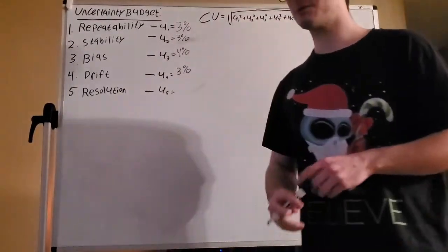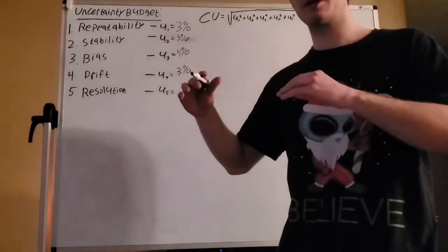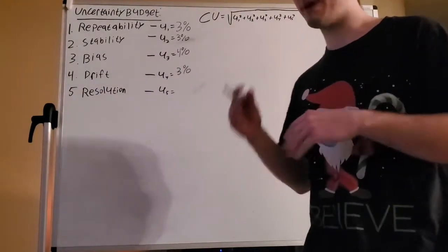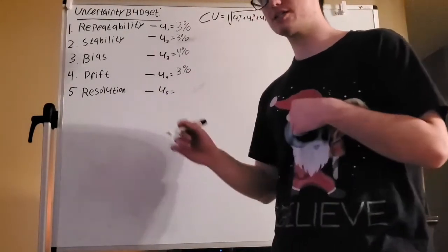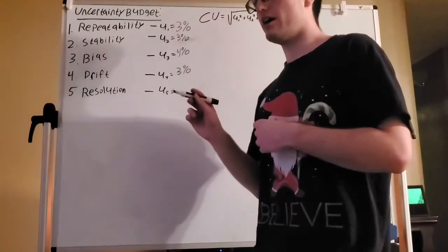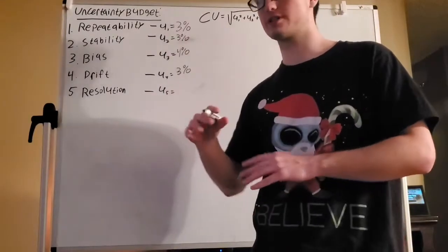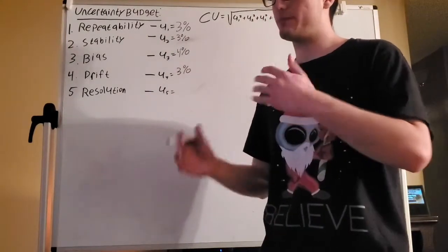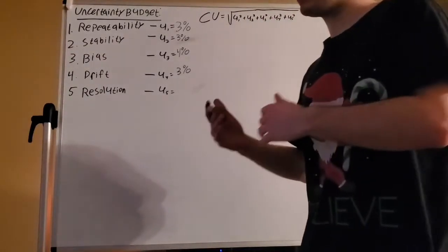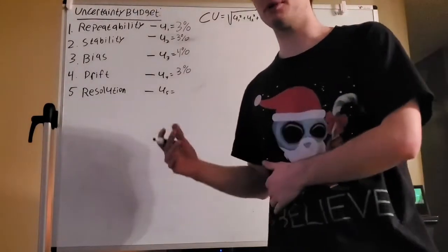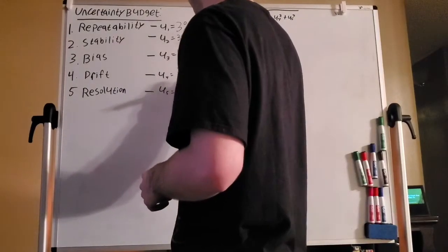Okay. And then the resolution is the biggest source of error in our experiment. The reason for that is how we're measuring the flow rates: we are measuring the amount of fluid that is flowing over a certain time. So what we did is we made marks on the tanks where the fluid was leaving and entering, and we just measured the time it took for it to go between those marks, which, using the naked eye, measuring out 10 liters or whatever amount of fluid we measured at the time, is not 100% accurate. There is definitely a source of human error in there. So because of that, we put our resolution up to 7%.